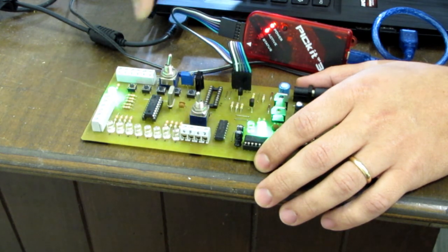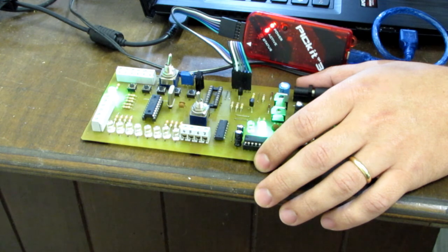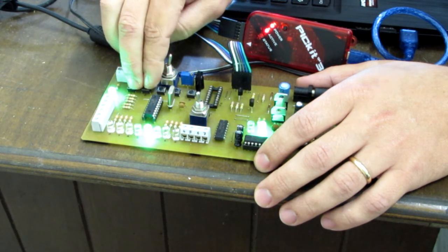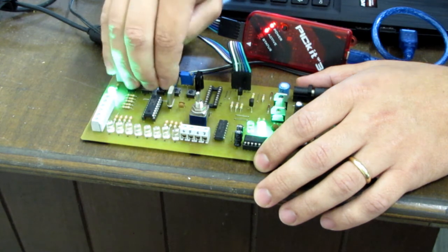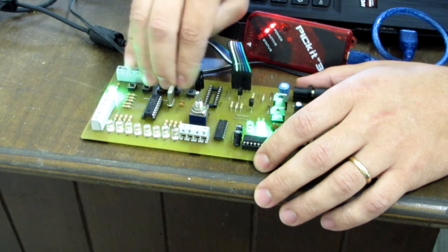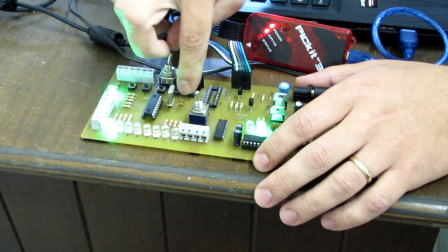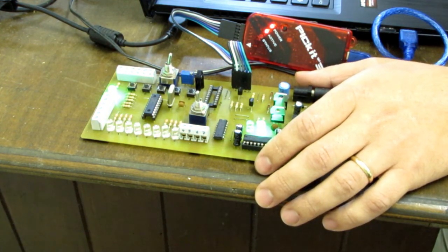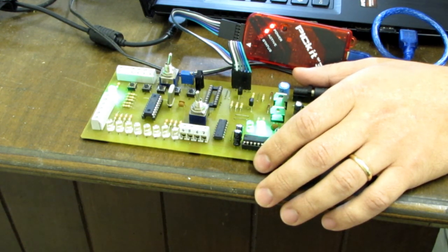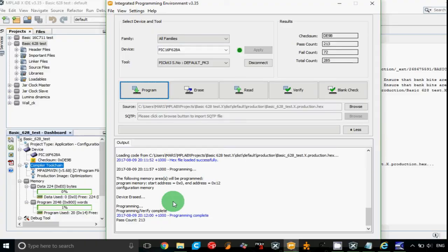I'm just going to hit it. This LED right here signifies that I have power on this side of the board and the microcontroller is already powered. Now if I press these buttons, I should be able to see these LEDs turning on. Check it out. I can even press multiple buttons at the same time, and the program will just read the entire value of the port. It will write it into the register byte, and then it will just copy that byte into this variable that we set, and from this variable it will just move it again into the output port, into the port B.